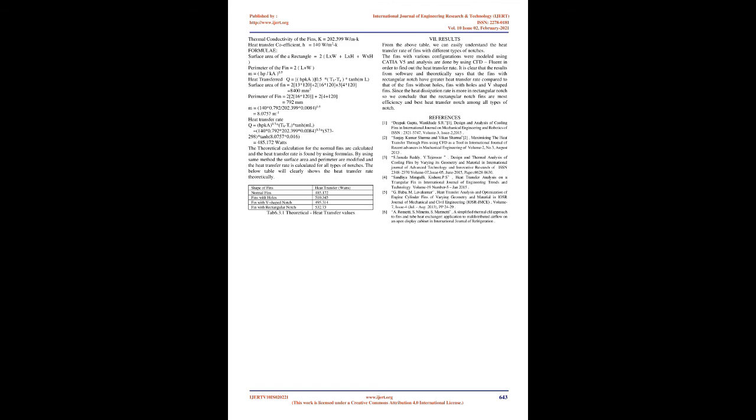Since the heat dissipation rate is higher in the rectangular notch, we conclude that the rectangular notch fins are the most efficient and the best heat transfer notch among all types of notches.